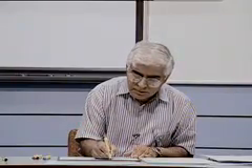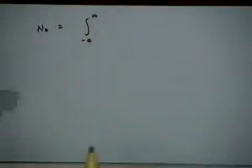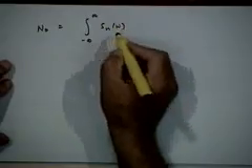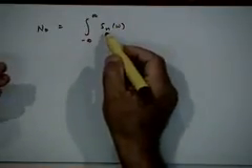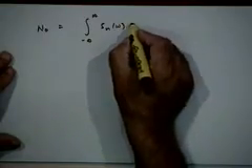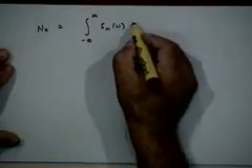What is the expression for output noise power? Let's say we are considering the general case, you could consider white noise, but let's consider a general noise which has some power spectrum S_n(omega). When you consider white noise, you can always put S_n(omega) equal to N_0 by 2, right. So S_n(omega) times, tell me, can you speak out?